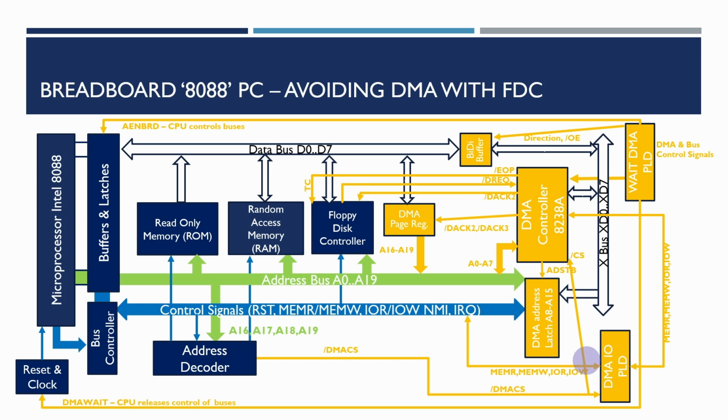Now, programmed I/O is theoretically not as fast as DMA in the original PC XT, just because they were using the basic 5 megahertz versions of the 8088 processors. But as soon as we got to 286s and higher, then programmed I/O was generally going to be faster than legacy DMA. So it's pretty likely that for this design and future designs, the trade-off of not using the DMA controller is not really a very great one. And at the end of the day, the DMA controller, I think in one of the earlier videos we said, could do about 400 to 500 kilobytes per second. Now the floppy disk drive would never be able to read data at that sort of speed, so it's really irrelevant from this point of view.